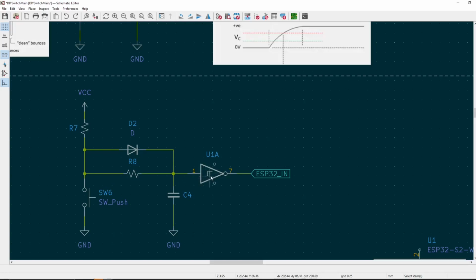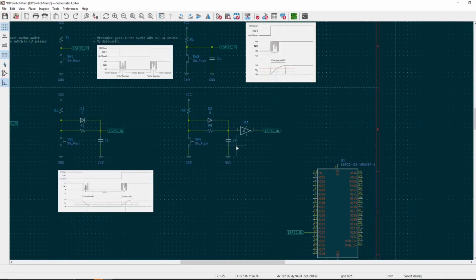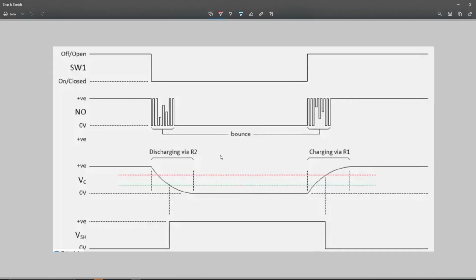We can add a simple inverter with Schmitt Trigger. What a Schmitt Trigger basically does is act as an inverter, just with a different threshold when it's going from high to low, and a different threshold when it's going from low to high, and that can be explained in the image here. So we have basically the same wave here with decreasing and increasing, but now we have multiple levels at which we detect logical high and logical low. So we have level 1 and 2 in our hysteresis.